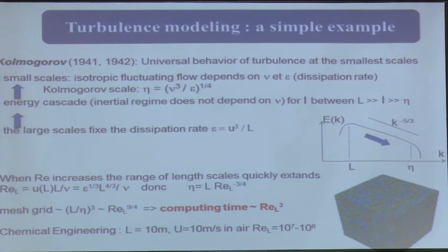But in some cases, the flow is very complex. And unfortunately, this is very often the case in the industry. So for example, LES models are working very well for very simple flows, like the flow in a square pipe or a circular pipe, the flow over a flat plate. So for simple geometry, LES are doing a very nice job. It means if you compare the real solutions with experiments with LES, you have very good agreement.